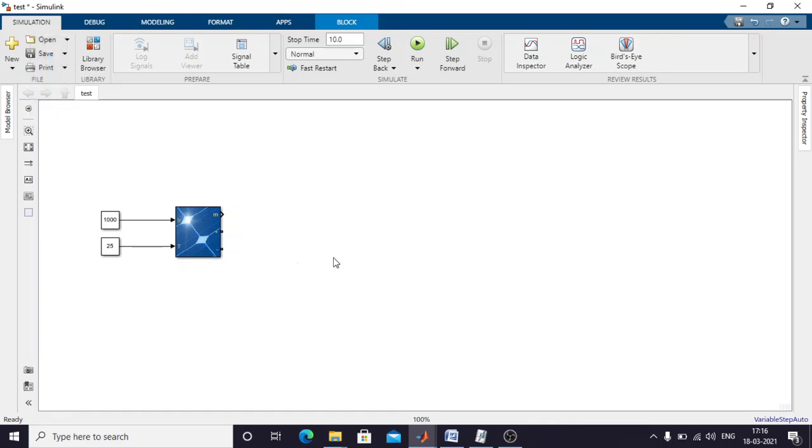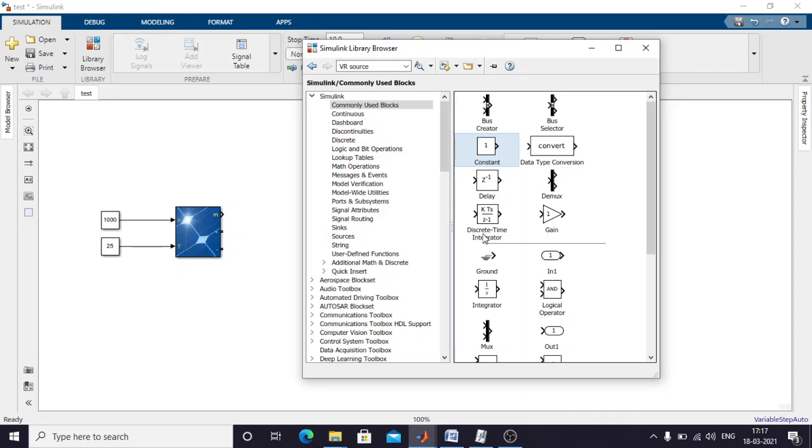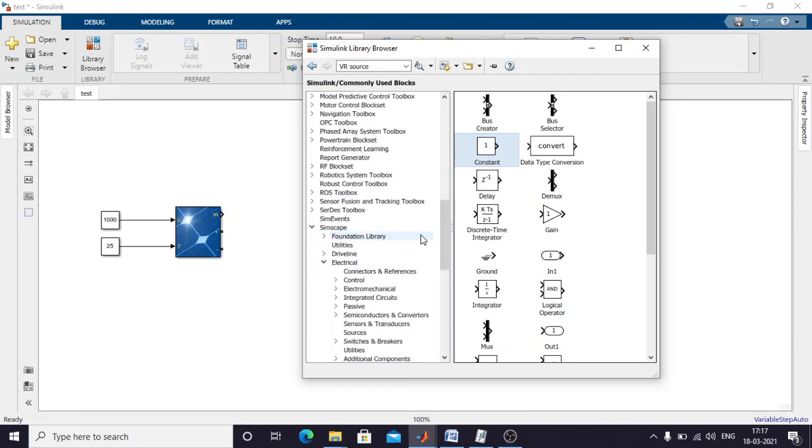So next we have to apply MPPT algorithm concept, as well as we need to connect boost converter after the solar panel. So for that we need a capacitor, inductor and IGBT.